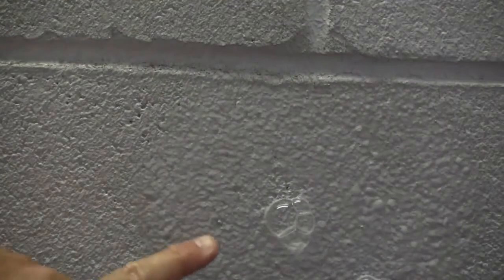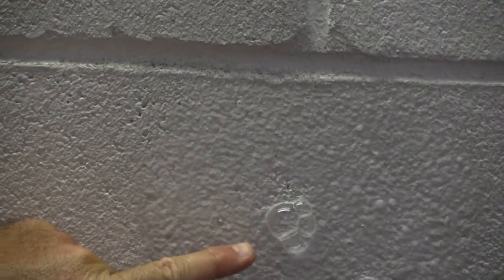If you look through the dome, you will see in the middle of the dome the formation of a bubble, indicating that an air leak has occurred. The surfactant in this case is bubbling up by virtue of the air being drawn through the block into the test chamber.